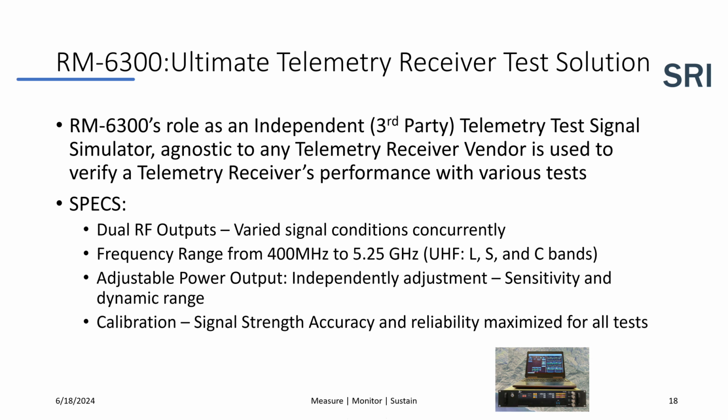Advanced modulation support. We offer several different modulation formats: BPSK, QPSK, OQPSK, 8 PSK, 16 PSK, and there are many others, up to 50 megabits per second, along with ARTM range tiers 0, 1, 2, also up to 50 megabits per second. Integrated testing suite.